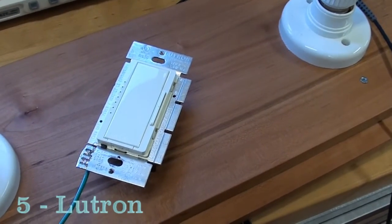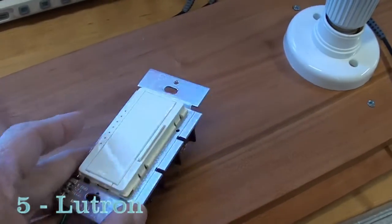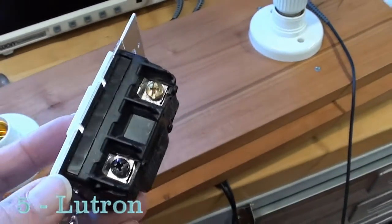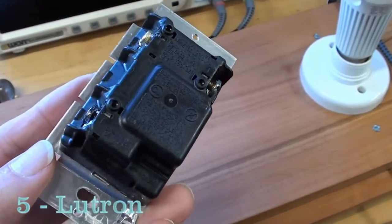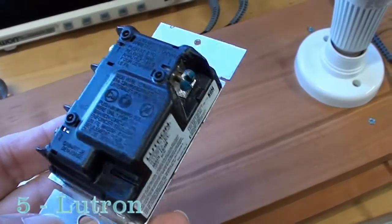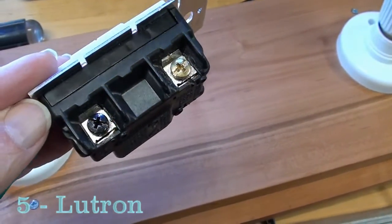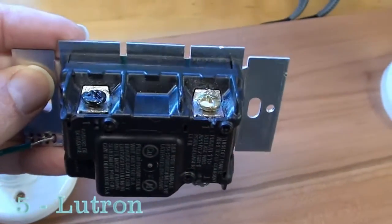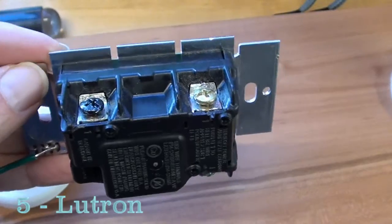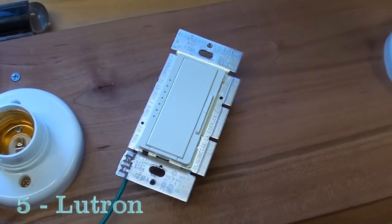The Lutron was one of the most stable waveforms in the bunch. It produced a very clean pattern on the scope, but it didn't really reflect any improvement in performance for the LED flicker problem. In a standard two-way configuration, it's a great switch to choose. That would be the 2-wire configuration.